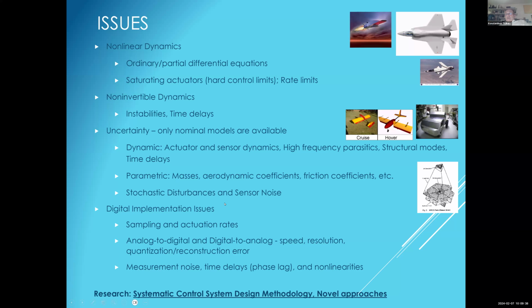On the implementation of controllers, things that do come up recently, because we are doing a lot more computer-based controllers and computer-controlled systems, we are interested in specifying precisely what kind of sampling rates we can use, how we can actuate, and how we can measure, dealing with issues with analog to digital and digital to analog conversions, and what kind of measurement noise we have.